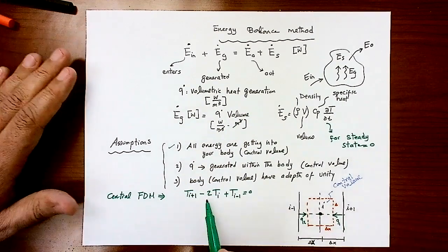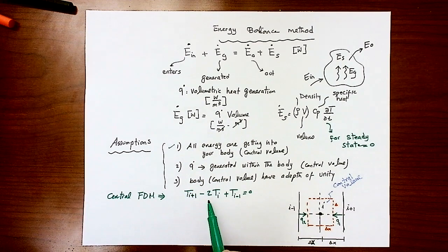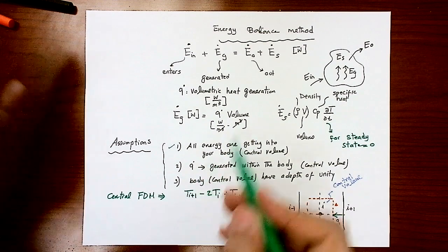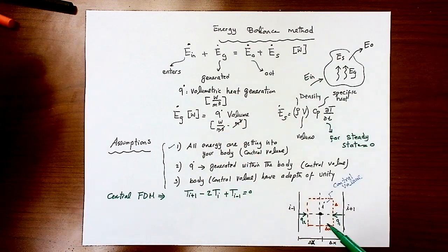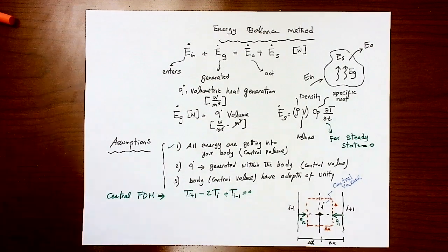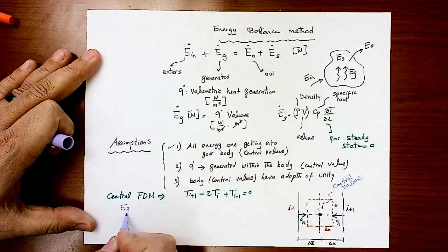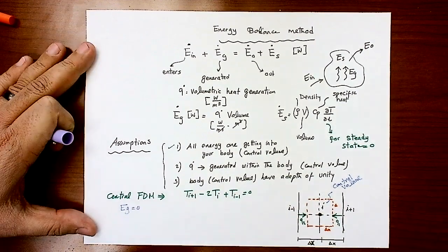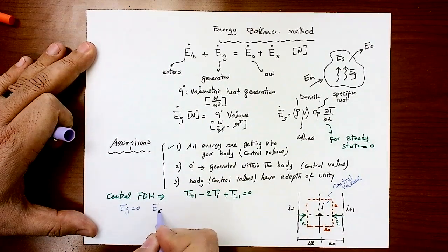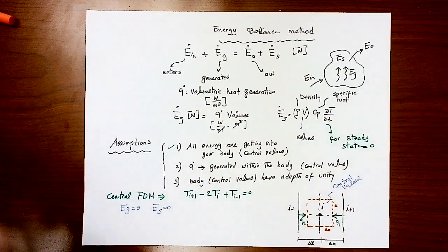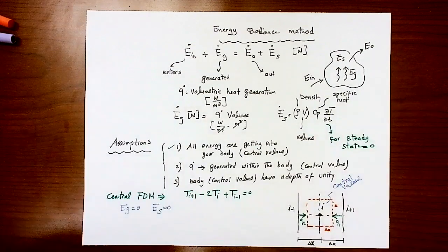But now this equation was based on no existence of any heat generation source. So I'm not going to include any heat generation in that part. So E generation will be 0 for that example here. Okay, so for that specific example here, we are solving here to match this equation. E generated is equal 0 because we didn't count for any internal source. Number two, we actually solve a steady state, so energy stored will be 0 because it's a steady state. So the energy equation, this equation, will end up looking like that.